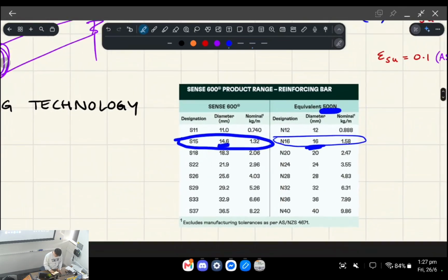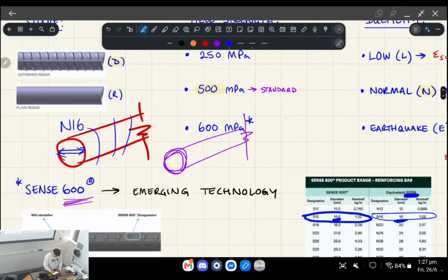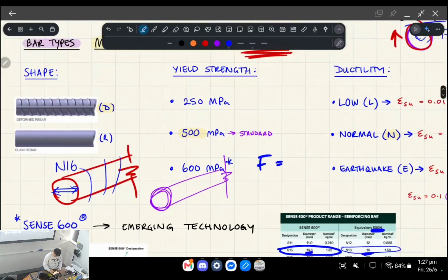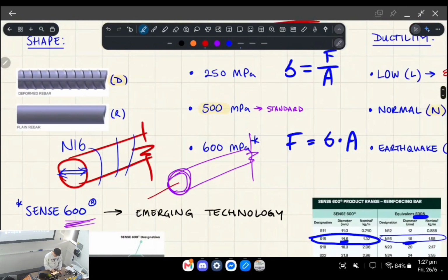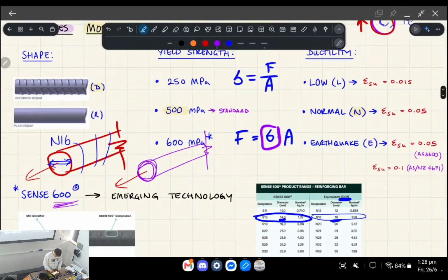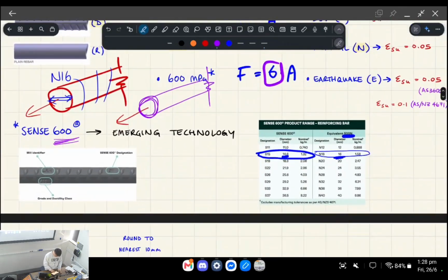And if you think about the equation, axial stress is equal to force over area, right? So if I rearrange this for F, the stress multiplied by the area is the formula for the force. So the idea is that you've got the same amount of force because you've got a higher stress, so you reduce the area to match, okay? So that's essentially how this works.